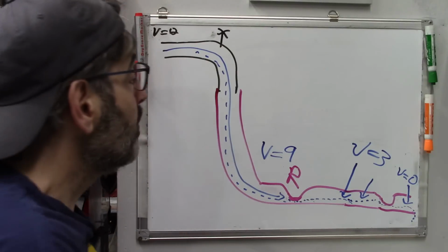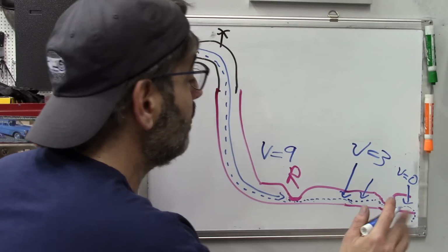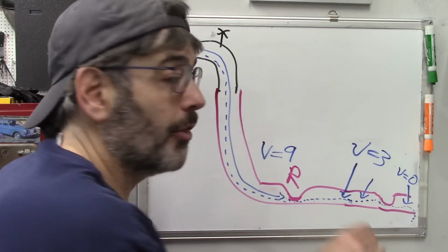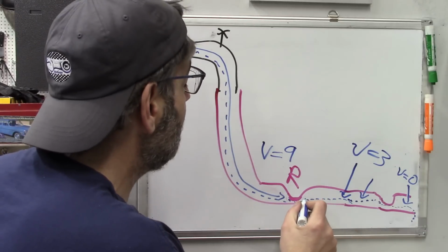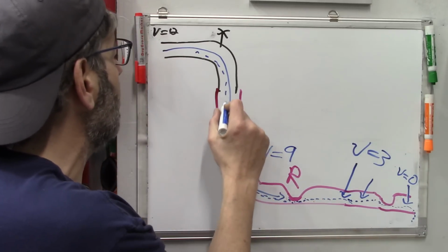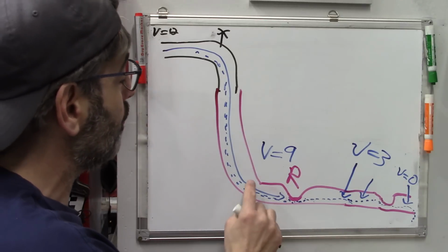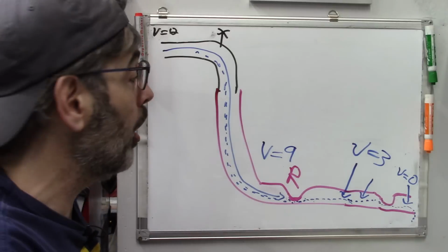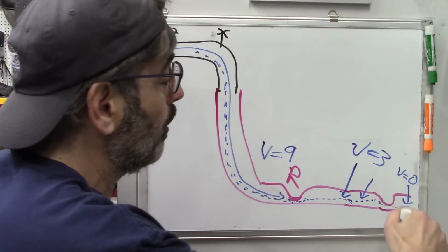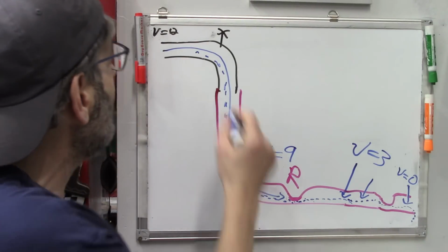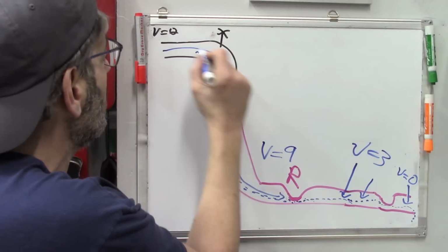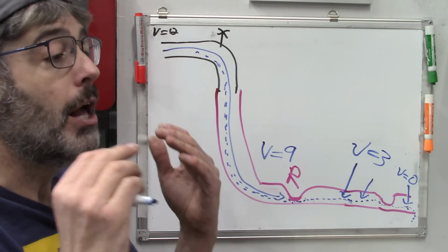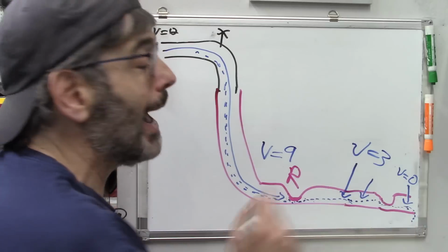Now, by adding this extra resistance in here, another kink to the hose, we've restricted, again, our current. The flow will be even less, and the effect of that is going to be throughout the whole circuit. So it's not like we maintain the flow we originally had. When we pinch that second part of the hose, we lower the flow for everything. Again, think about it. How can you have a faster flow anywhere along here if you have a slower flow here? It all has to be the same. The current will be the same before or after a resistor.